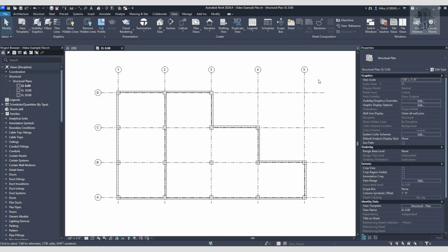In this example here, we're at the bottom elevation of this structure. And as you can see, we have column grids where there are no columns. So what's going to happen is if we leave these as is, the 3D extents will be out to the full max. And we're going to have to edit the 2D extents in every view that we create moving forward. And we don't want to do that.